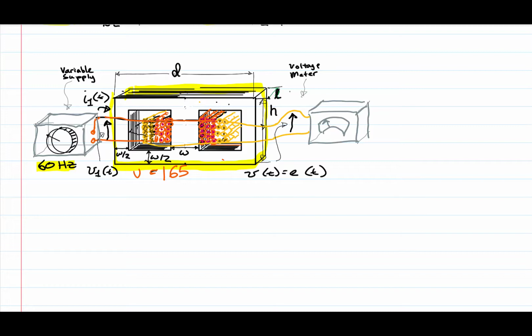And with the EI core structure, you usually have a laminated core structure where the laminates consist of an E shape. And notice that the middle leg is exactly twice as wide as the side legs. And then it's pressed together with a bottom I lamination piece here.